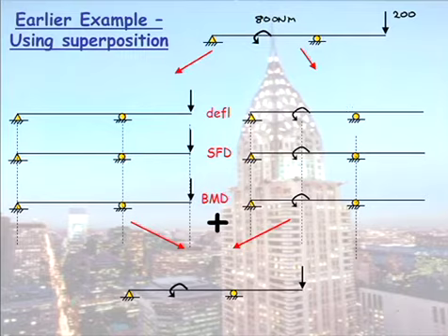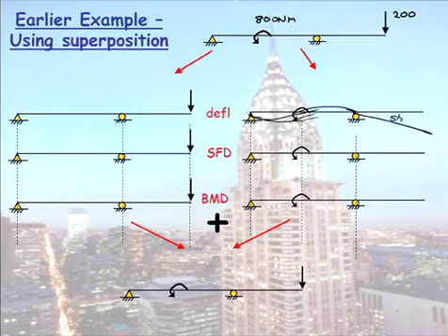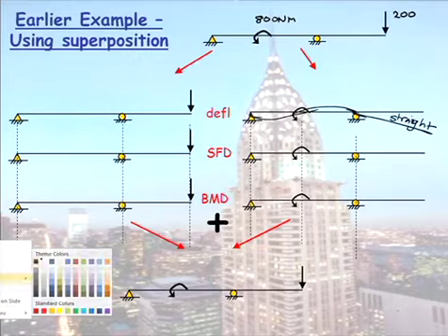With this deflected shape, it's fixed at the 2 supports, well, it can't move, and I'm rotating it down. So I am, in fact, and I'm not drawing this very well at all, getting that shape. Now, this bit here, beyond the support, is straight. It's only moving down because at the support it's been rotated around. So that would be my deflected shape there. Now that's such a bad deflected shape. Let's just take away that bit there. So hopefully you can all see that deflected shape.